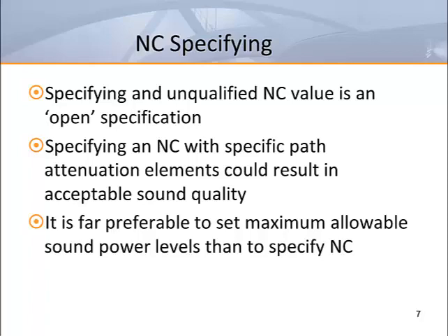Although it would be much better to include sound path attenuation that all vendors should consider, the very best approach is to set maximum allowable sound power levels that all vendors must meet. This simplifies the submittal process for all parties and eliminates any guesswork. This is by far the best way to ensure that acoustical design goals are going to be met.